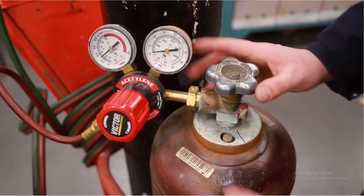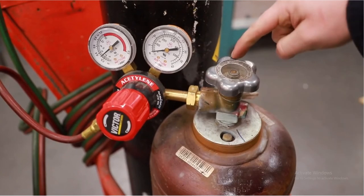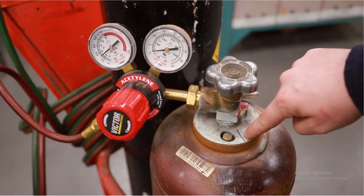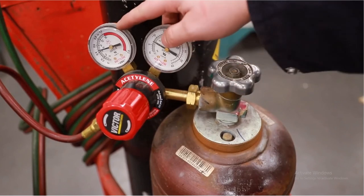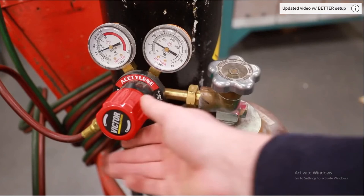First, we're going to do the acetylene first. We're going to open up the main valve here half a turn. So if this is my start, I want it to get to here. And I've drawn a little line here to help remember. Half a turn. Now, the last person who used this did not purge the valves, but usually when you get to it, let me just purge that valve for a second.